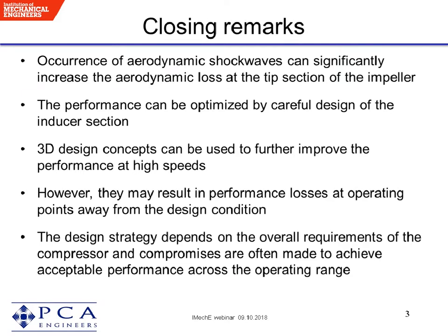That obviously limits the choke flow at high speed. So then you start to compromise the design by applying more turning or more aggressive design of the tip in order to open up the throat. That has consequences in terms of efficiency, but that's one of the ways you can widen the map.